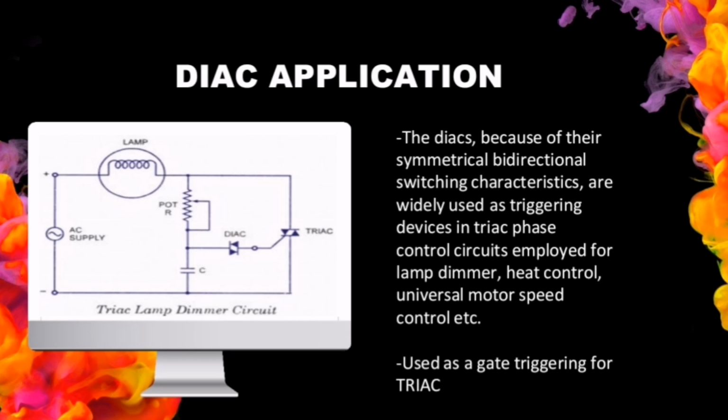This results from the fact that the diac switching characteristic is far more even than that of the triac, since the diac prevents any gate current flowing until the trigger voltage has reached a certain voltage in either direction. This makes the firing point of the triac more even in both directions.